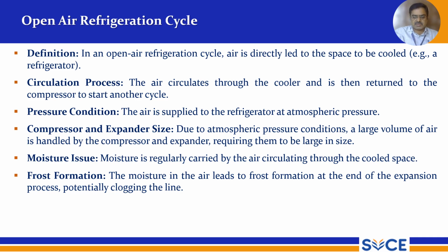So moisture is the main culprit due to which the frost is forming here, at the end of the expansion process, potentially clogging the line. Once the frost is formed in the line, it will clog the line. It will not allow the air to circulate comfortably.